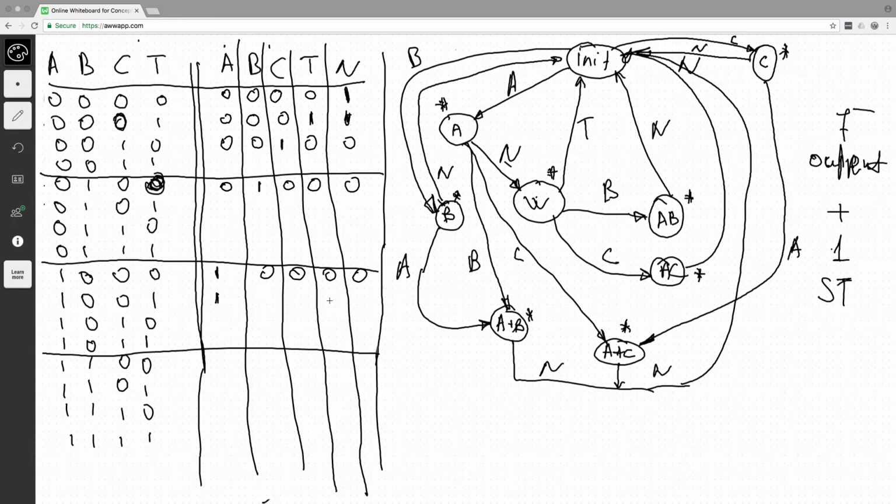Can we say that T is expired? No, we cannot, because if we put 1 in this position, not 0 but 1, it means that A and expired T will result in expiration of the timer. But it contradicts the logic, because we're only interested in expired timer when none of the key is pressed. So that's why here it is 0. All right.